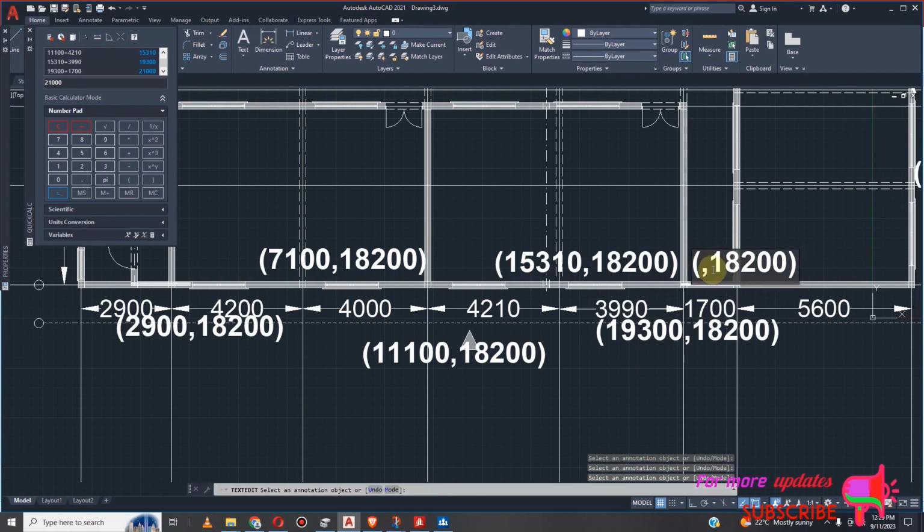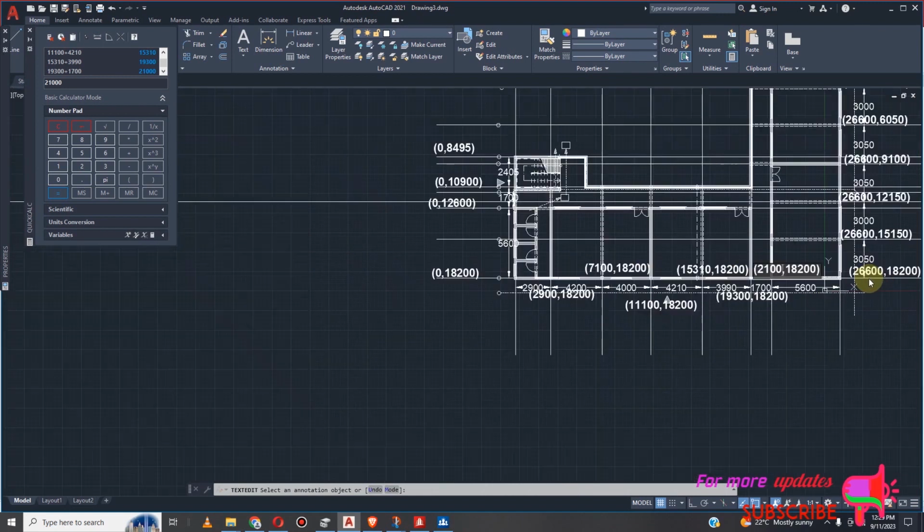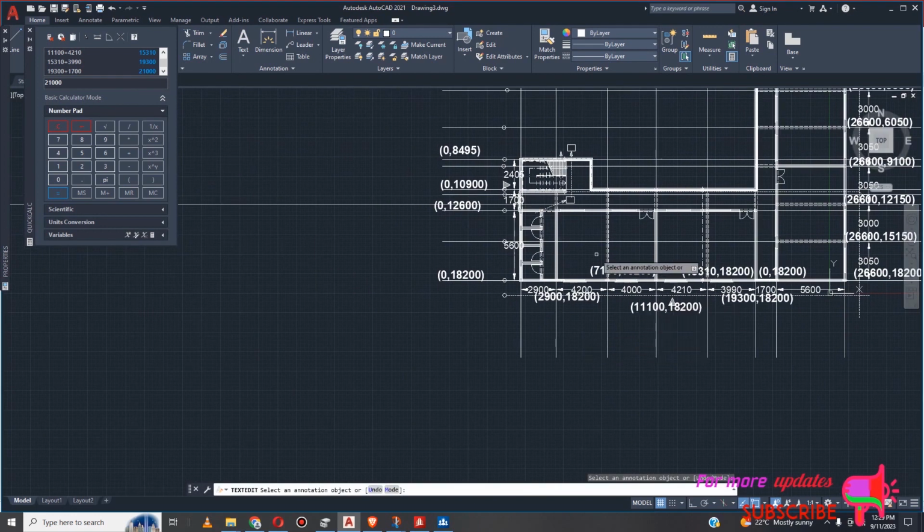So a lot of work will be just adding these coordinates, but after we put these coordinates in Excel and copy paste them in STAAD.Pro, we will just model very fast. So I just copy these ones because the top portion is also similar. I will just change in the Z direction, right? So copy, drag it to that point.